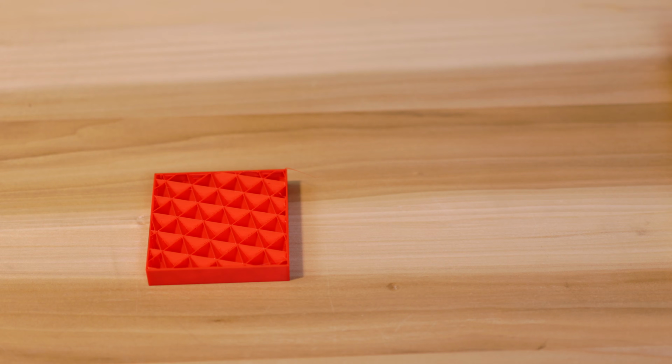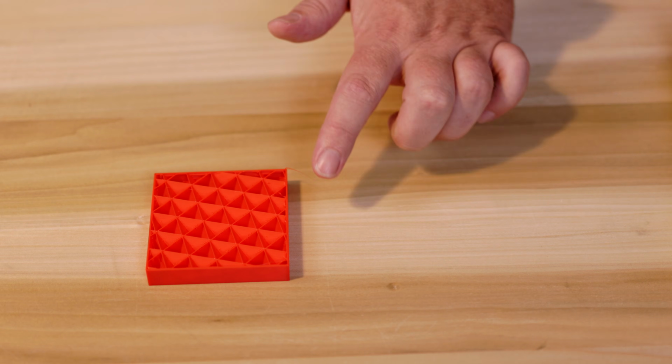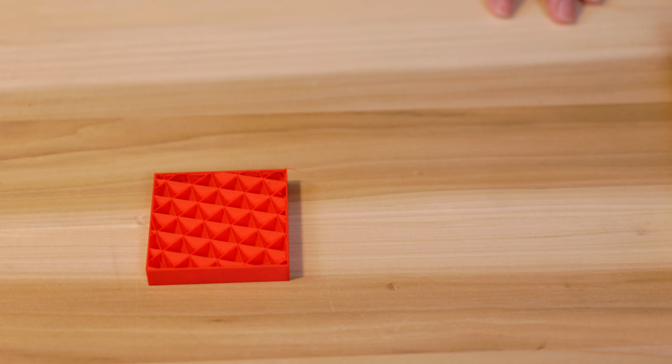All right, and next is cubic. Cubic is 3D cubes that rotate orientation with each layer. The use case are parts that require equal strength on all sides or in all directions. The pro is multi-directional strength. The con is it consumes a lot of material. And the printing tip is consider infill density based on the strength that you need. This did take 1 hour and 4 minutes to print with 68.77 grams of material for this particular cube.